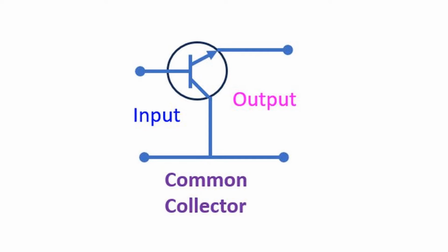Base is the input terminal in common collector configuration, also known as grounded collector configuration and emitter follower. It is called emitter follower because the emitter voltage follows that of the base, though the emitter voltage is lower by an amount equal to the turn-on voltage of the base emitter junction. Here output terminal is the emitter. Gamma is the current gain in common collector circuit.